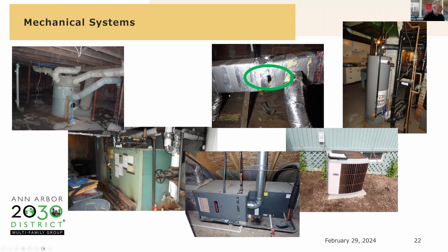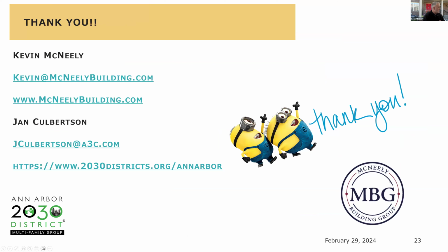That's a big hole in an air conditioning duct. And there's another one up top here that I just noticed. So make sure that all those get sealed. That was blowing air conditioning, cold air into the attic space. Same with your water heater. Replace that with an air source heat pump. They're significantly more efficient than gas and electric resistance. And then same if you got split systems. That is it. There will be a checklist coming out for when you do turnovers.